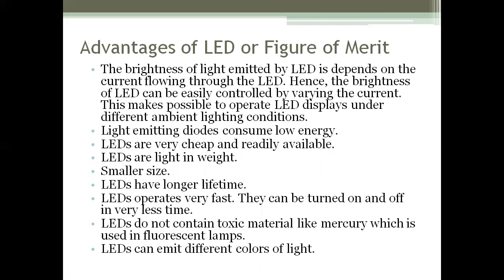Coming to the advantages or merits of an LED, the brightness of an LED can be varied very easily depending upon the current flow through the LED. If you want a highly intense output, we should give more input, and if you want a less intense output, we should change the input to lower values. So it can be easily controlled by varying currents. This makes it possible to operate LED displays under different ambient lighting conditions.